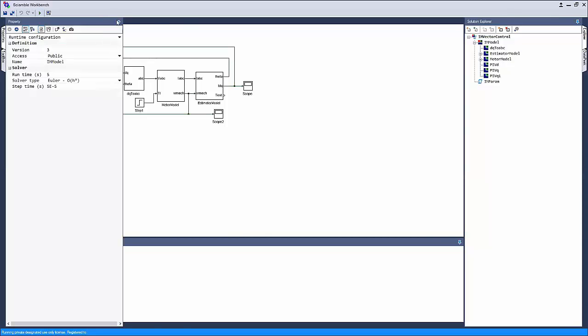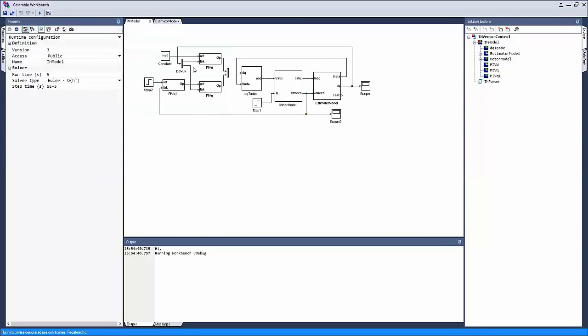So for the D-axis current, we can control two components now, the D-axis current as well as the Q-axis current. In a DC motor, we could only control one component because there was only one control variable, which was the applied terminal voltage. But in AC motors, you have two control variables, namely the magnitude of the applied terminal voltage as well as the frequency of the applied terminal voltage. In a balanced system, you can't adjust the phase shift of the applied terminal voltage.